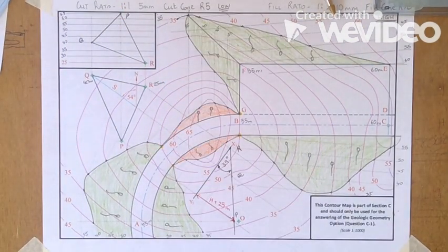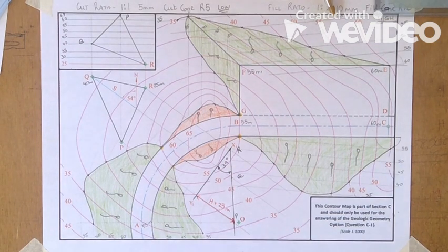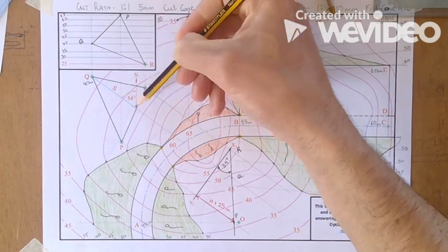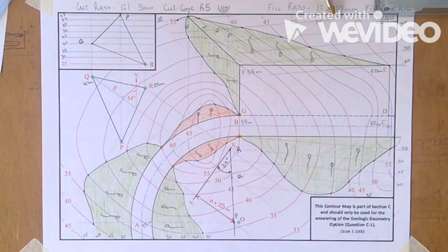Okay. Now the last part then is to determine the true angle between the line PR and the strike line S. Okay, so the true angle they want between this strike line here and this line PR. Now, to get that, we need to be looking directly onto the top surface of the stratum of ore. So there's a couple of ways you can do this.